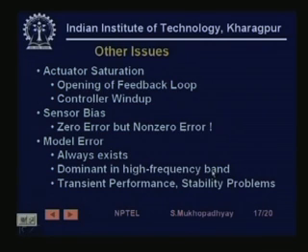Remember that instability typically occurs in the high frequency band, not in the DC or lower frequency band. So if you have modeling error in the high frequency band, then such modeling inaccuracies can also lead to stability problems. So we have to remember these things.